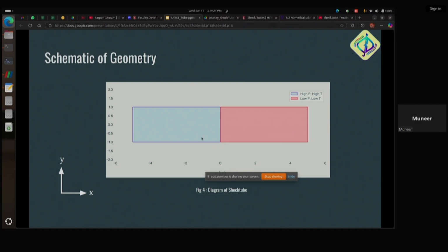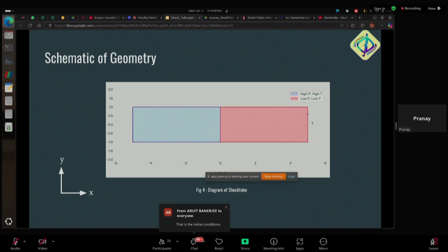The usual approach when we model something is to model an inlet, which says the pressure is coming in with some value. Then you would have to define another inlet, but that would mean deciding what happens at the junction of these two. And this becomes a wall, this becomes a wall, and this becomes a wall. So reflections come from many different points.